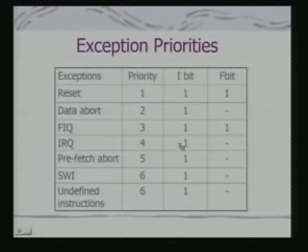Now, you will find that for all these interrupts, the I bit is getting disabled. So, normal interrupts are getting disabled. Inside the service routines of these interrupts, if we are not explicitly enabling the interrupt, a general interrupt cannot be serviced, but FIQ can be serviced. So, obviously, you can realize that FIQ has much greater weightage associated.